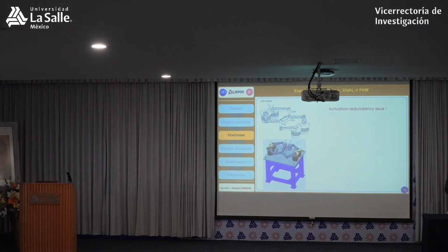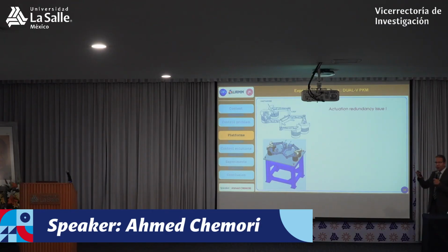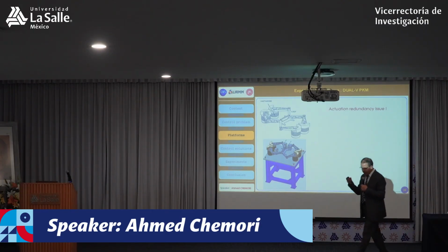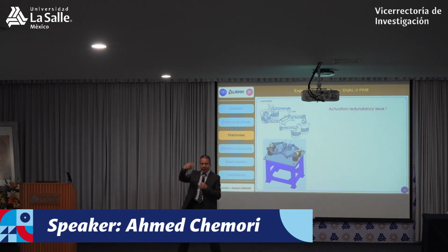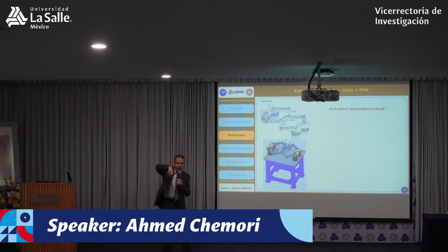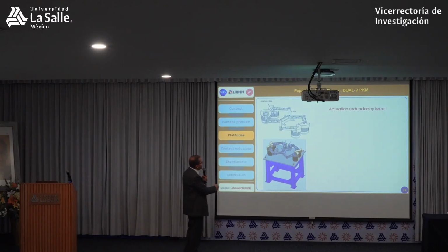The next one is something else which is different, and here we are interested in machining. If you want to do machining using a laser, you have a laser cutter. A laser cutter, you can fix the head here, and the idea is to follow a predefined trajectory to cut the material, following a predefined trajectory representing the form of the piece that you want to cut. So you fix it here.